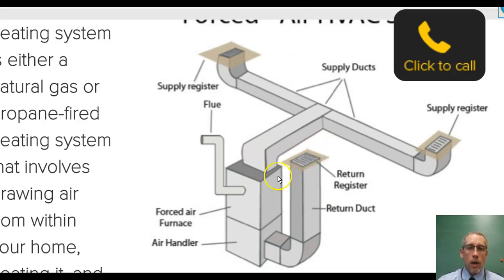And so you'll also have in every room, or maybe there's just a few throughout the house. In newer houses, they tend to be a lot more open, and so you might have one spot kind of in the middle of the house with a big vent, and that's the air inlet. Now, sometimes it's hard to tell where the air is coming out and where it's going in, but if you just feel when the furnace is on, do you feel air coming out? Or if you take something like a little tissue and put it up close to the air return, you will actually see the tissue being sucked in towards the vent.